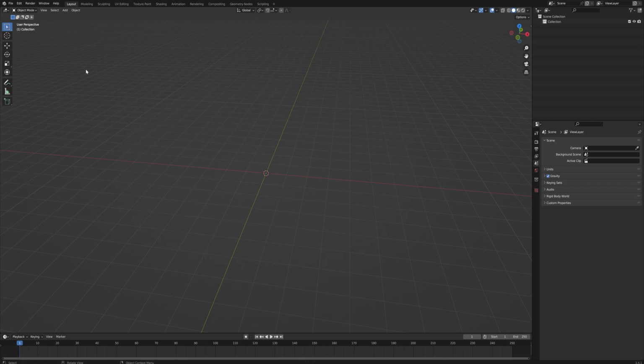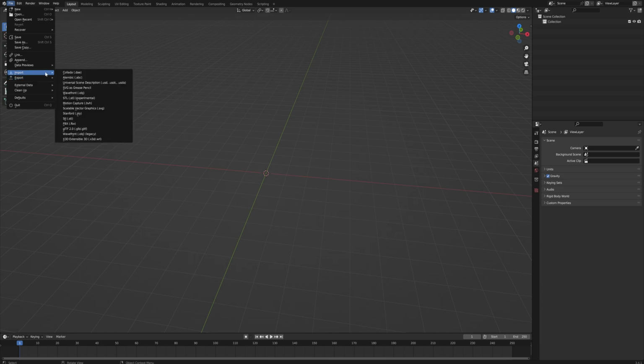And it's important that you have a vector image. That's why I was showing you that in Illustrator before, because we're going to come up here to File and Import, and we're going to import a scalable vector graphic file. That's an SVG. If you have a different type of vector image, like an EPS, for instance, which is a very industry standard format to use for vector images as well, there's a lot of online converters where you can just upload your EPS file and download the same file but in SVG. So we're going to just import that.